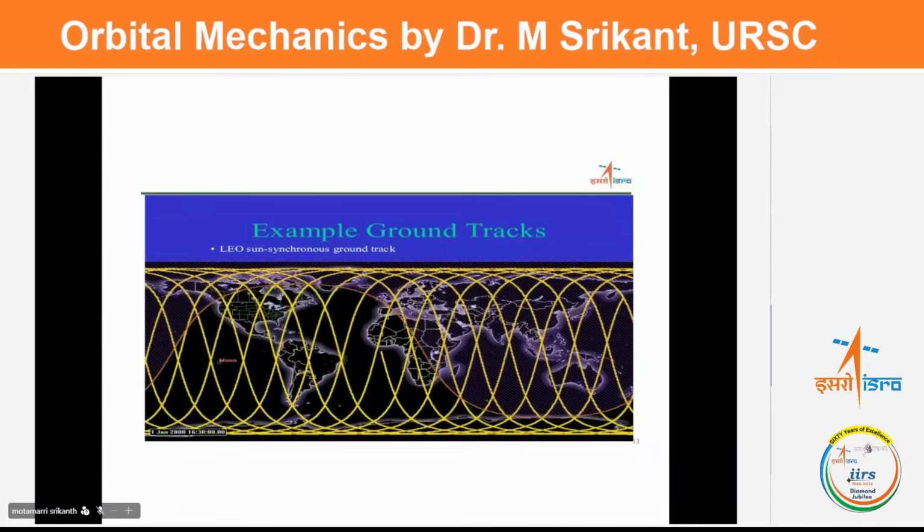One question is, why do satellites at higher altitudes stay in orbit longer than those in lower orbit? Very good question, sir. Take a case where one satellite is in a 300 kilometer orbit and another is at 720 kilometers. The basic difference is the drag effect that comes on the satellite because of the lower altitude. Aerodynamic drag plays a critical role.